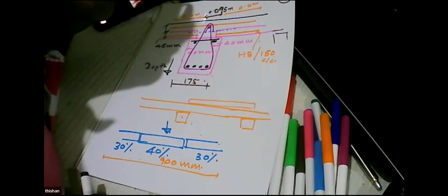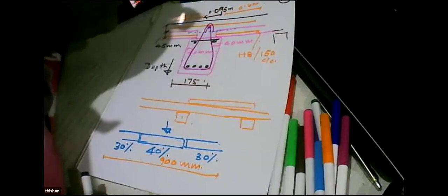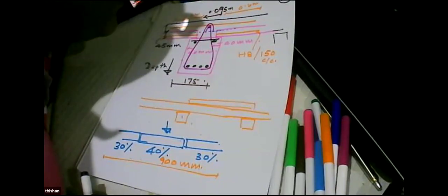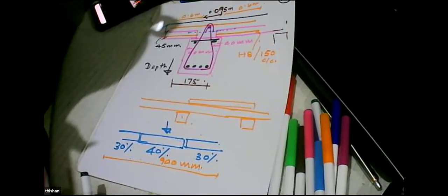What about the reinforcement covering? As it is less than 20 millimeter, will there be any issue with the durability? No, we have selected 15 millimeter as the minimum according to Eurocode, because we are using high strength concrete, compacted very well. And we can easily cure the steps, because after about 24 hours you can make it vertical and then carry it.